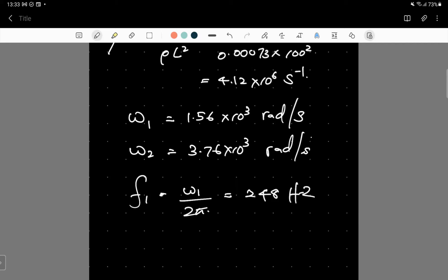However, when the system is discretized, let's say to n number of segments, only n degrees of freedom are created, and the lowest modes and frequencies are approximated most of the time when we perform calculation, and the higher frequencies are mostly damped out more rapidly and are of less importance.